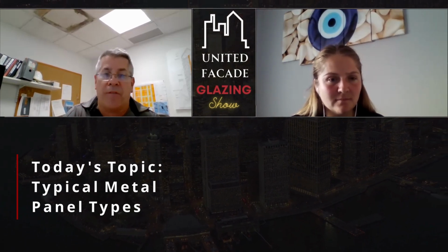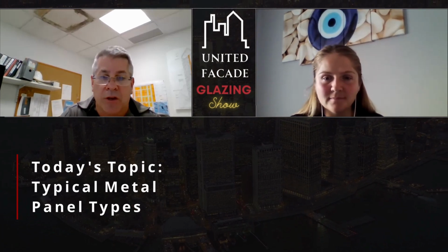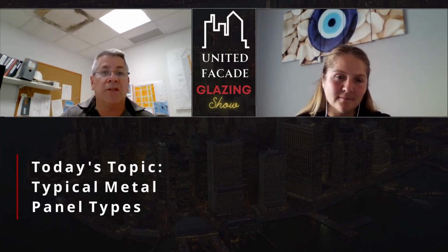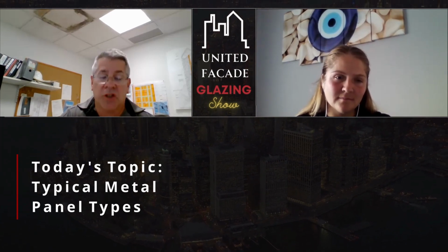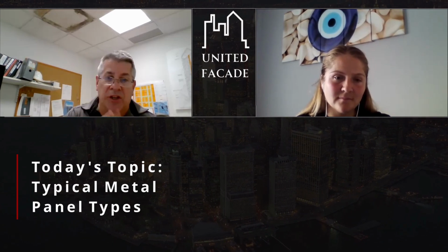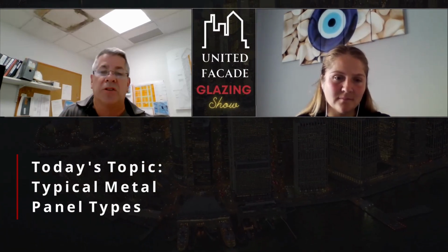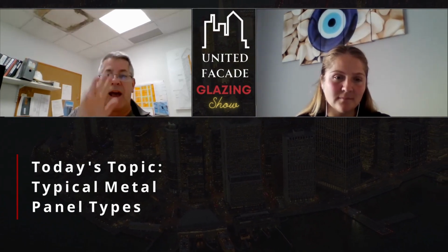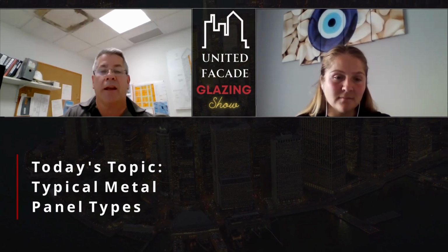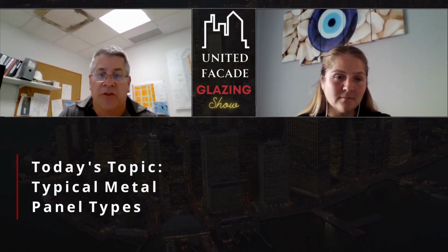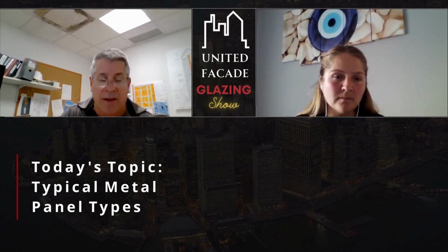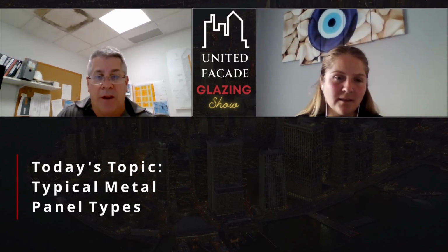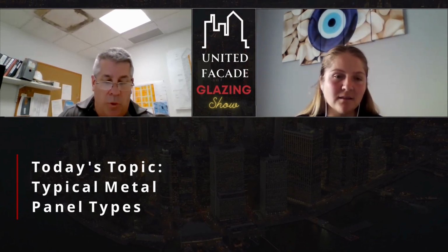whereas aluminum can be a very fine and flat finish, very glass-like, very smooth. Bronze, although it's going to be smooth, you're also going to get striations in it where you're going to almost have graining. It's a little bit like wood, where if you oxidize it or you stain it, you get some of that graining look on it. And again, a lot of architects like that look, so at times they might specify that just because of the look you get, whereas you wouldn't get that with a painted finish. So that would be one of the reasons why you do it.